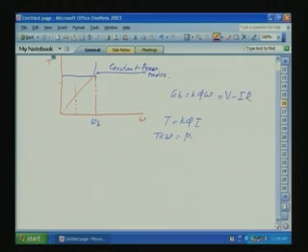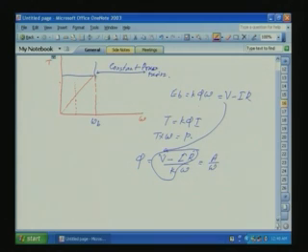From this one, what is phi? Phi is equal to V minus I R by K omega. R is constant, I is constant depending on the rating, V has also reached the maximum value. So if you see here, all this gives a constant value. So phi will be equal to some constant A by omega. Now, let us take phi is equal to A by omega.